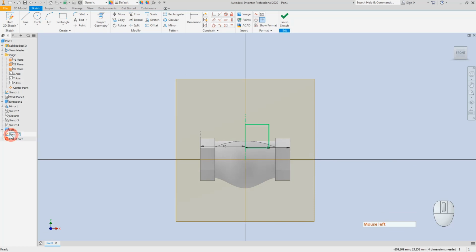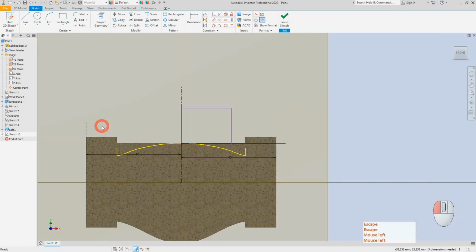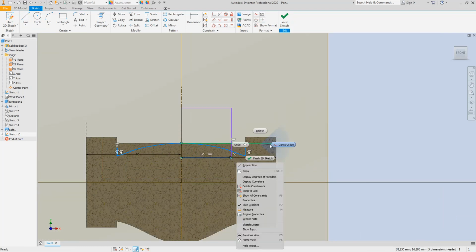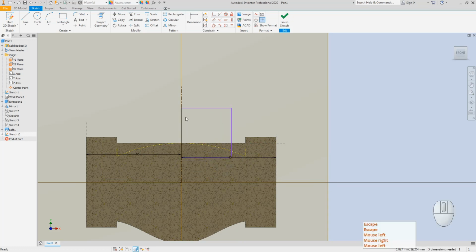This one, again, start a new sketch. We have at this point the rail on the top side. It's a straight way. I will just make the first this projection, the geometry here, the top side, this lines or this line intersection, whatever it is. I will just take this line and convert all other lines to construction instead of this one, because I'm just going to make a join operation.